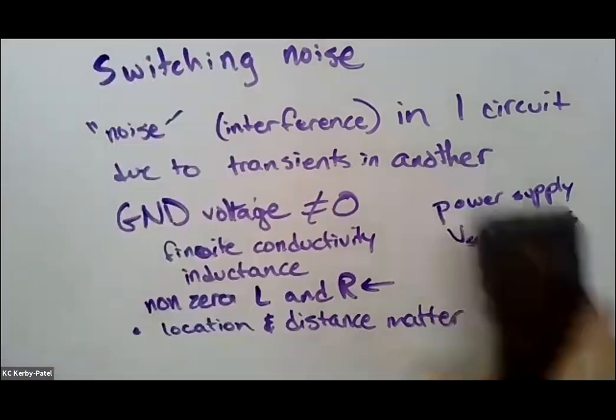When you are dealing with RF circuits, if you are wiring a circuit up, like in one of your labs in another class or something like that, and it has anything that is operating at a moderate to high frequency in it, right? If you think you might be hitting up against that lambda over 10, maybe we should think about transmission line effects, circuit size. Think about this.